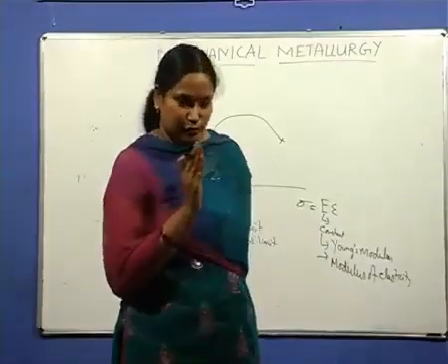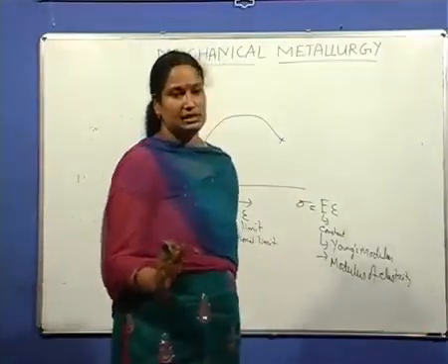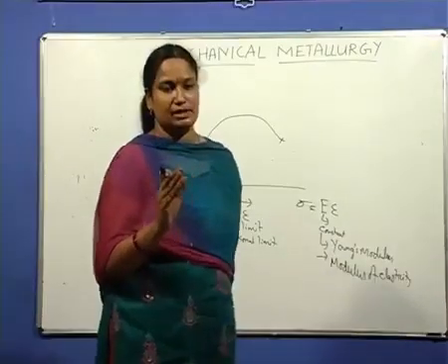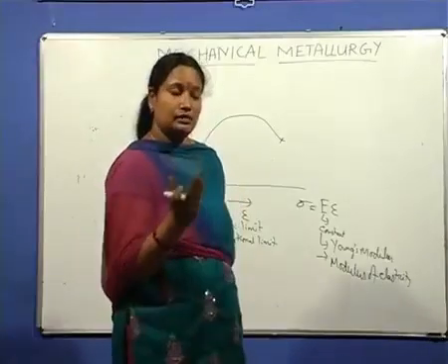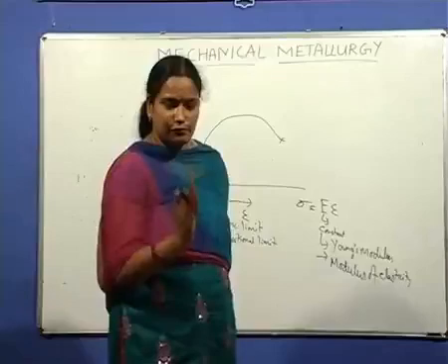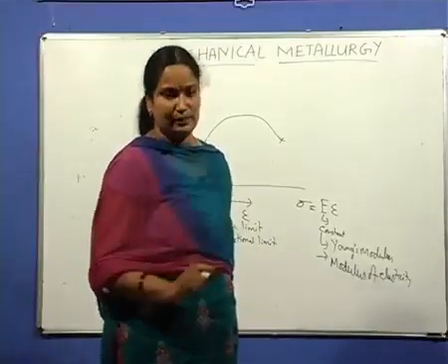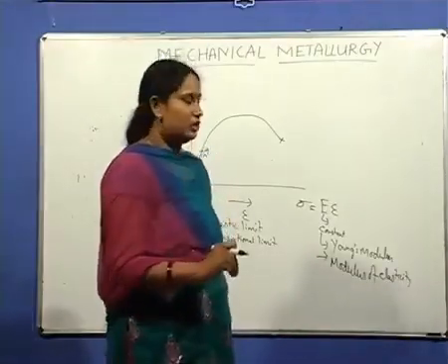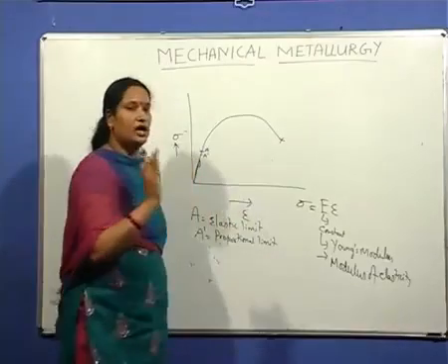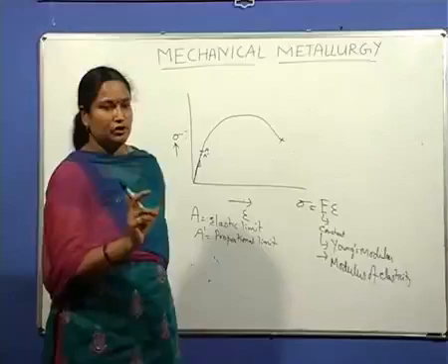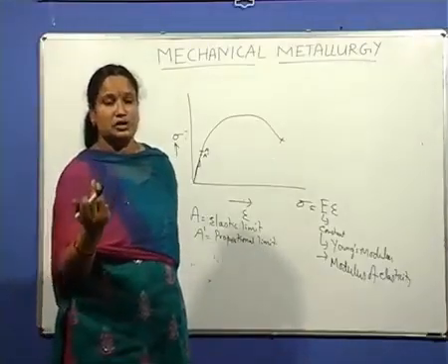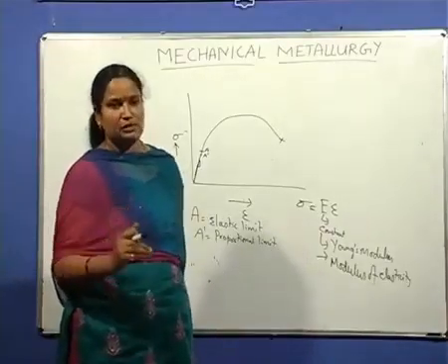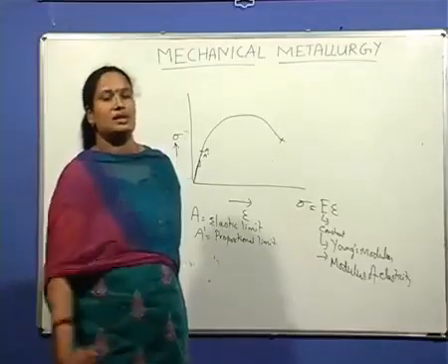The importance of this constant, Young's modulus, is that it indicates the resistance of a material to elastic deformation, or in other words you can say it indicates the stiffness or rigidness of the material. Resistance of a material to elastic deformation is stiffness or rigidity of the material. How rigid or how stiff the material is depends upon the parameter Young's modulus. Higher the Young's modulus for a material, the more resistant it is to elastic deformation. Lower the Young's modulus, the less resistant it is to elastic deformation.